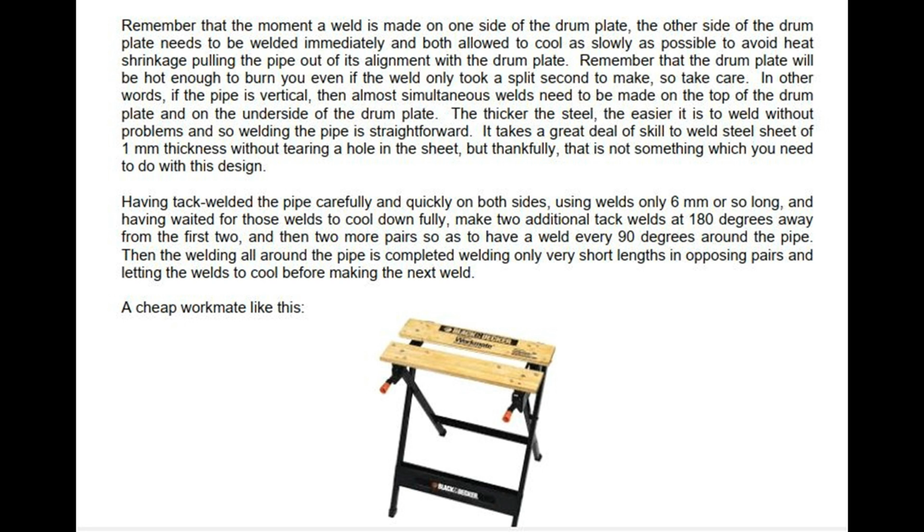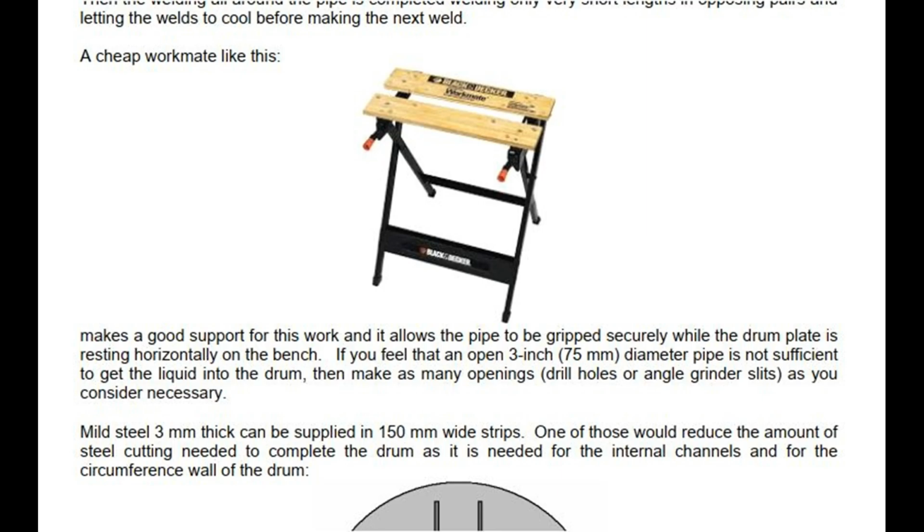A cheap workmate like this makes a good support for this work, and it allows the pipe to be gripped securely while the drum plate is resting horizontally on the bench. If you feel that an open 3-inch, 75 mm, diameter pipe is not sufficient to get the liquid into the drum, then make as many openings, drill holes or angle grinder slits, as you consider necessary.